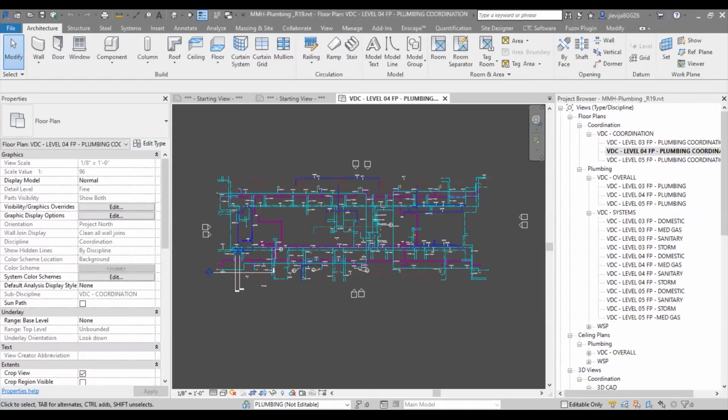In other situations, when we're running piping and ductwork, we're going to make sure that not only do we have our piping going either under or over top of our ductwork accordingly, but that we're accounting for all of the insulation, and also for all hangers that are going up to mount to deck. So that's the difference between where we see things coming out of a design firm or architect's office, and moving into the contracting industry within VDC.